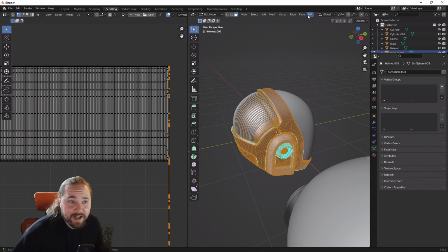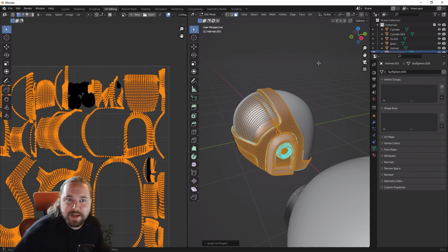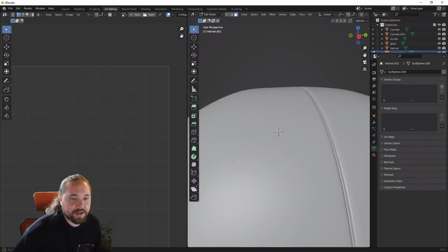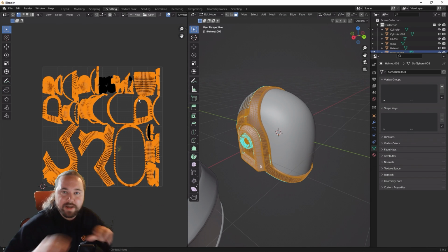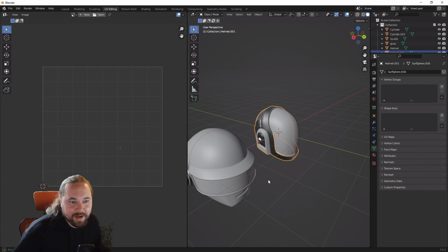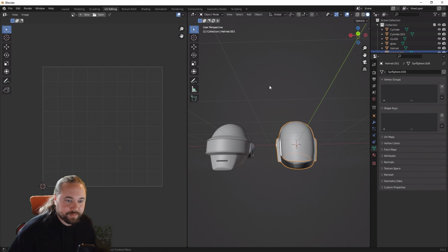If you have something like that, it's at least worth a try in Blender. If you go to UV editing, go to UV, and try something like Smart UV Project. As you see, it's gonna do its best to automatically lay out, like a piece of paper craft, essentially. Lay out the UVs, so the 2D texture connection on your model.